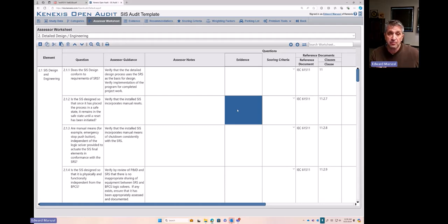So in this case, for part 1, we were interviewing the HAZOP LOPA team. For part 2, we're interviewing the SIS engineer, maybe people at site, maybe people at a systems integrator, maybe people at a detailed design contractor. But you don't just rely on their word, you get paperwork to prove that they did what they did, and maybe you're actually going to do a visual inspection, go out into the field and watch a test be performed.